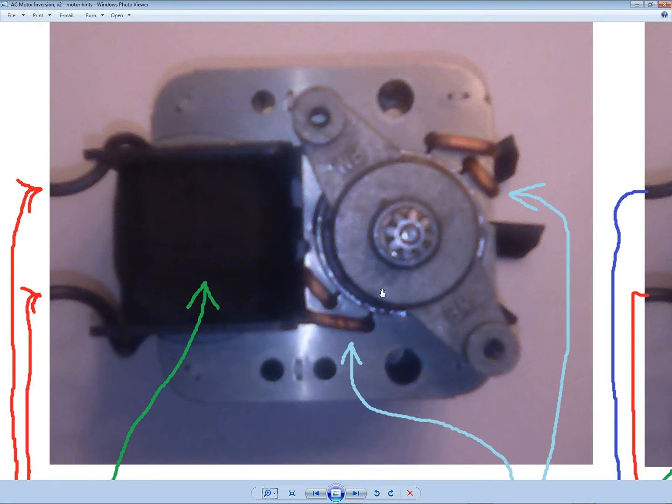And the squirrel cage turns freely, and this is one blade of a fan on the opposite side to help cool the thing. And this is one plate that you're looking at of, I don't know, maybe 20 laminate levels or layers that are stacked going away from us, okay? And then there's a bobbin here, a plastic bobbin, that goes through a slot down here, goes through all the laminates, comes back the opposite side, and comes back over to here. And then what we're looking at here is tape, a cloth tape that surrounds the windings. And I peered into the edge here, and I found that it was very thin enameled magnetic wire. I'm assuming it's enameled magnetic wire. But very...